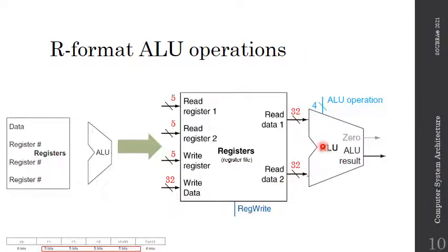Awesome. There's something missing in that figure. What would that be? Something interesting. So ALU, R format: I'm choosing the source registers, two of them, and I'm choosing the destination register. And here I can see that I've read the two source registers and used them in the ALU. What should I do next? Well, the result should go back to the register file. So basically, the connection that is missing here is from the ALU result all the way back to the write data input here.